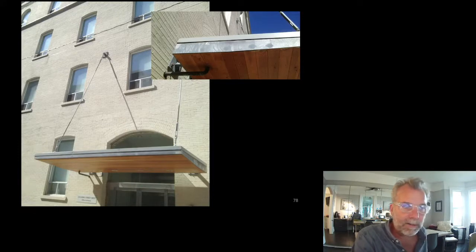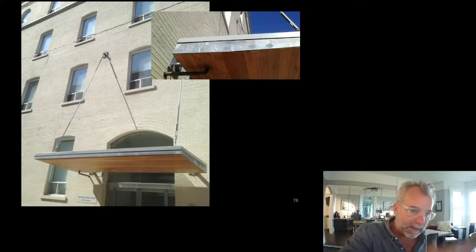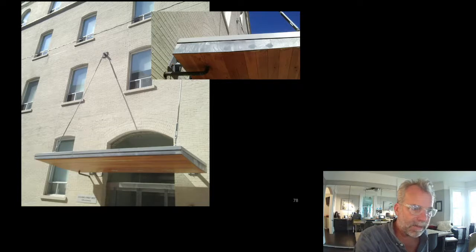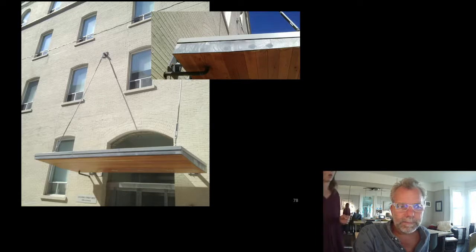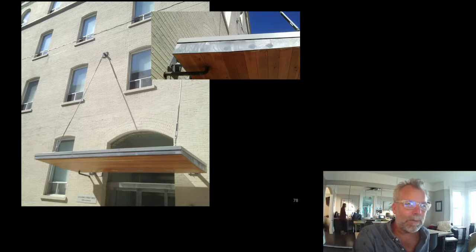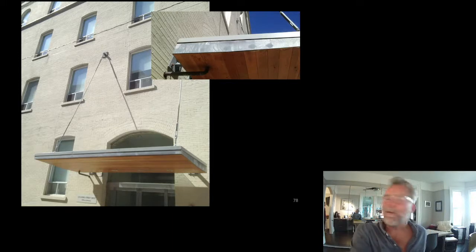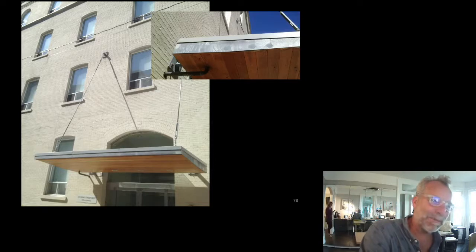There are other strategies to do this. We have done this by ballasting the roof as well. You just make sure that there's enough load on it that it can't lift up. And that's an effective strategy. And that the ballast is a reasonable ballast that won't be blown away in the windstorm that is also causing the uplift. Right. So we don't ballast it with stacks of greeting cards, because they blow all over the place, right? Or fine gravel. That's also bad.